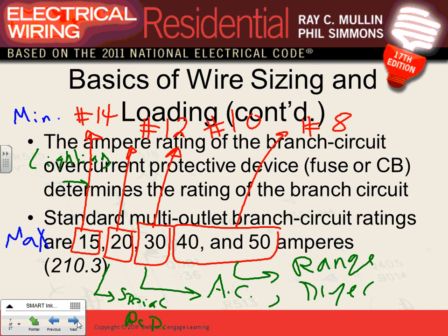Now question number 2 is how many conductors do I need with each one of these circuits? Minimum. Can anybody tell me a minimum how many conductors do I need? Minimum, we need 2. The ground always goes without discussion. The ground, we don't count it. When we say conductors, the ground goes without discussion. We need 2 conductors. So for this circuit, you need 2. Anybody can tell me why? Hot, neutral. How about this circuit? 2, typically hot, neutral. How about number 10? 2, typically the 30 amp for air conditioning or dryers.